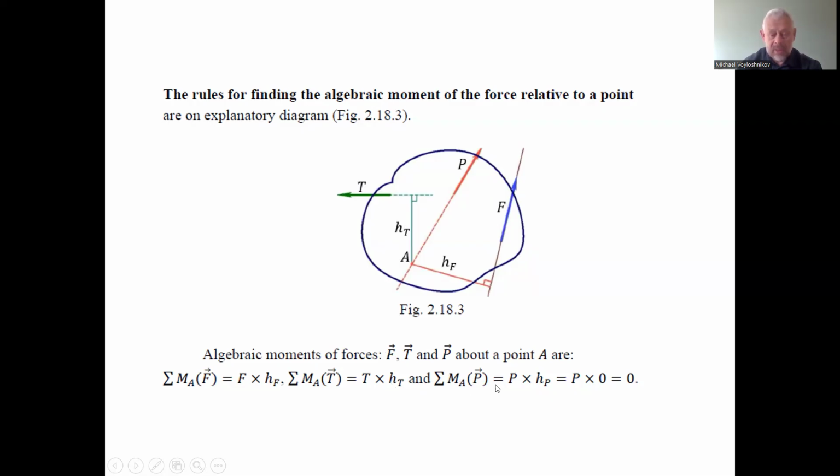Just set the moment equal to 0. Finally, we can change the rules of the signs. Just multiply the left and right sides of the balance equation by -1. So the signs change on the left side of the equation, and 0 multiplied by -1 remains 0, so the right side has no change.